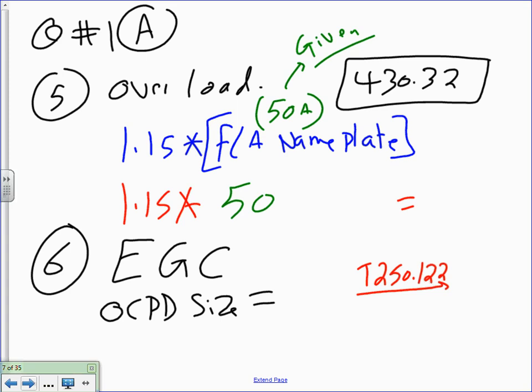It's 55 in the NEC code book, but I went to the nameplate for this example and read 50. That's what I'm giving you. If it's not given, we go to that table and you use 55. Very good point. Almost always, 99% of the time, it's given, guys.